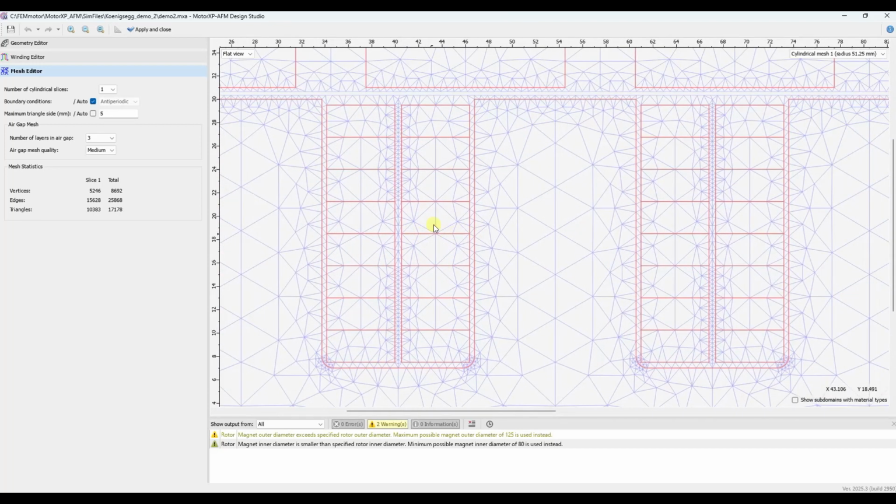conductors here. I'm just saying because now that you have a transient solver, for sure, I imagine, let's say through MATLAB, you can input as well a non-sine wave current input. And eventually, if you want to simulate PWM, you go to the skin depth of the conductor, and therefore, it will be interesting to have a skin depth mesh as such. Not sure if for you to implement it, if you are thinking to add a tool just to have a skin depth mesh, or eventually execute a piece of code in MATLAB to put it, or did you think about this? I mean, if you want to have a skin depth mesh on each turn of the coil, right?